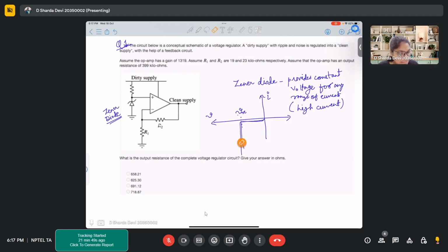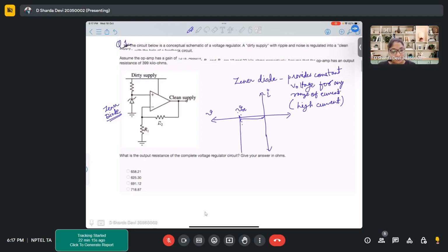After this particular voltage, the voltage across the Zener diode never increases. So no matter how high a current you push through your diode, your voltage remains fixed. That voltage cannot be changed. That's why the output across a Zener diode is always fixed, and why Zener diodes are used for voltage regulation.